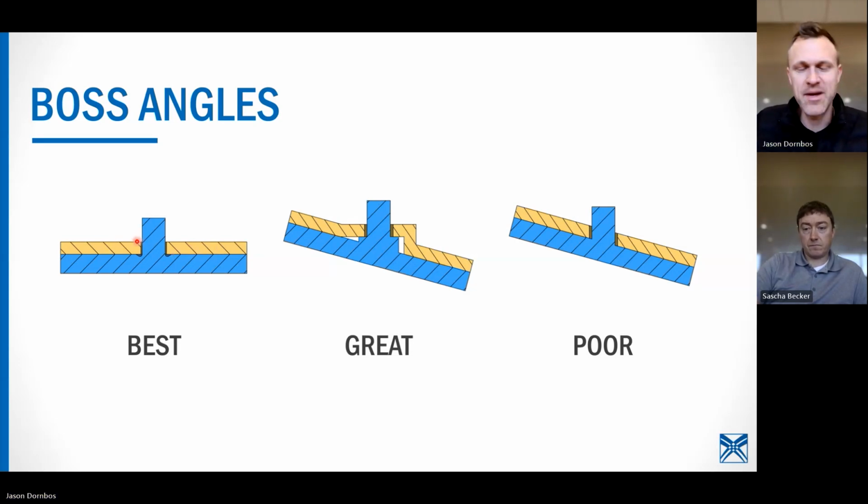There, because the material itself is maybe kind of soft and easy to tear, to get a good strength what we typically want to do is take your stake head and spread it really far so that the flexible hole in the mating component can't stretch around the boss head. But in both technologies, yes, you should be able to stake flexible materials. It's just you're kind of limited as far as how strong they're going to be.